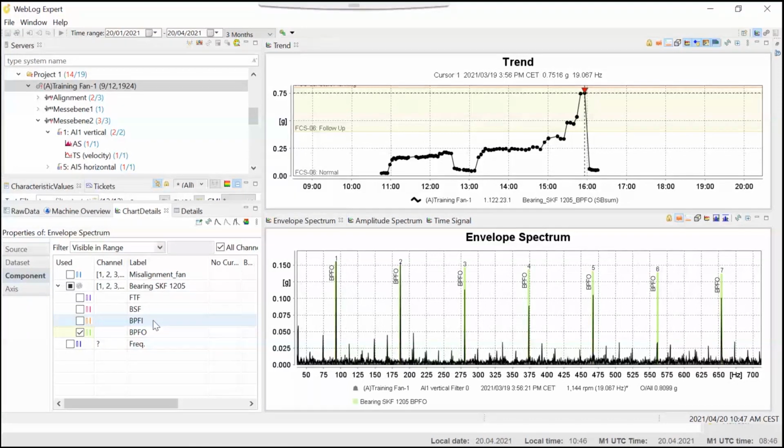That's right, yes. You'd be able to say, oh, that's probably a bearing fault, but you wouldn't be able to say which bearing it was unless you had a list of the defect frequencies. So it's much easier after we've done this post-processing to extract those frequencies and compare them with a list of what we have as likely candidates.